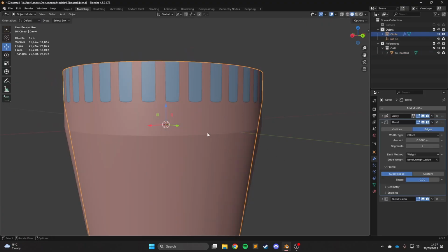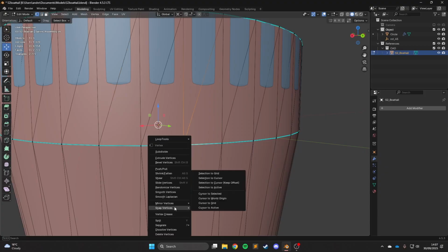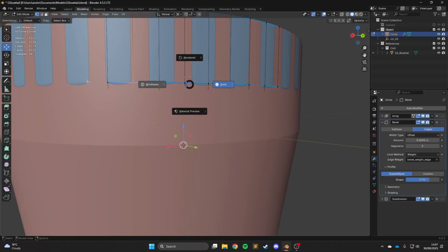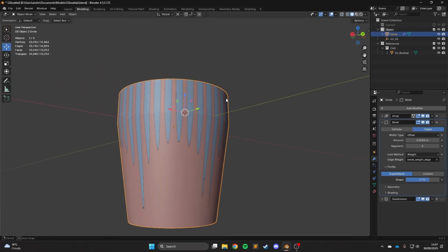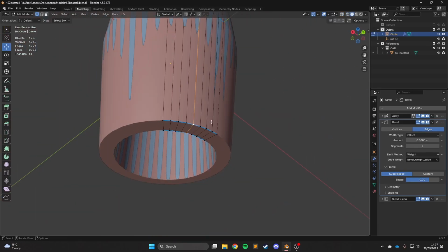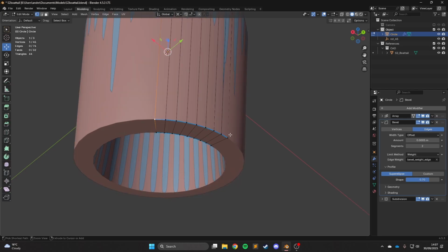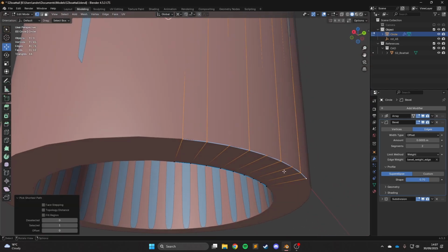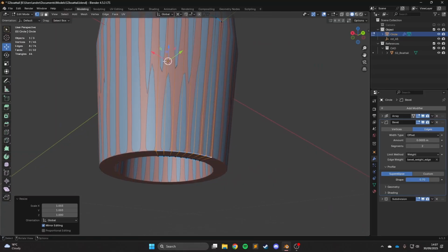We're trying to create this here. So what we're going to do is the same trick as before. Flip the cursor to here, and then S Z 0. Get along there. And now, actually if I snap the cursor back to the world origin, I can get a more precise kind of angle on what this should be here. So we're trying to go for about half and half on both.